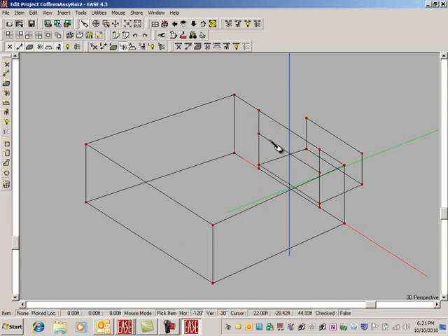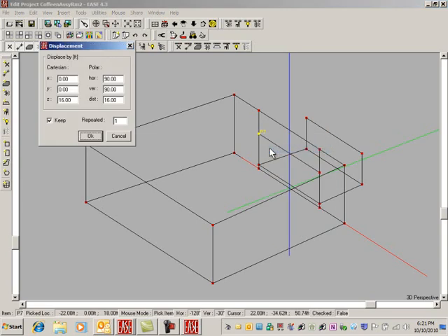And the vertical angle is up. Might need to use a little trigonometry here. It's up 2 feet and 21 feet. And so if we want the angle, we could look for the sine of the side opposite over hypotenuse. 2 over 21. That'll get us pretty close.